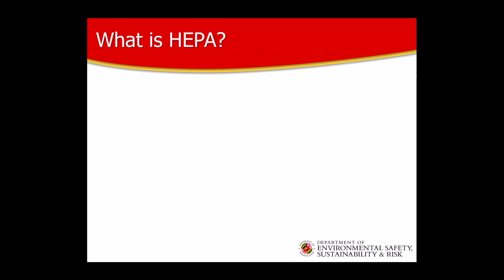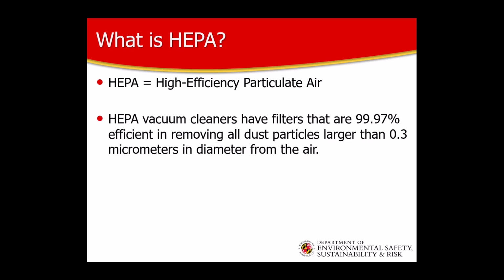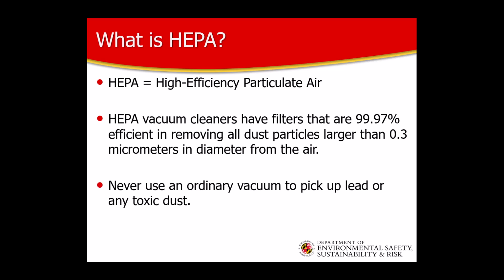As mentioned, using a high-efficiency particulate air, or HEPA-filtered vacuum, is a recommended work practice when cleaning up. We should never use an ordinary vacuum to pick up lead or any toxic dust.